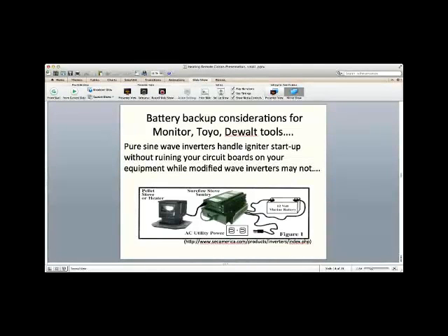And therefore, you wouldn't want to just put jumper cables on your 12-volt battery and take the negative and the positive and clip them on to the 110 plug of the pellet stove. You instead, in the middle, want a pure sine inverter. Pure sine inverter. And that helps to take care of the transfer of electricity where you can use it for heat. If you try to run one of these pellet stoves without electricity, it's not going to fly, even though you have fresh fuel going in there by an auger or a gravity feed system.